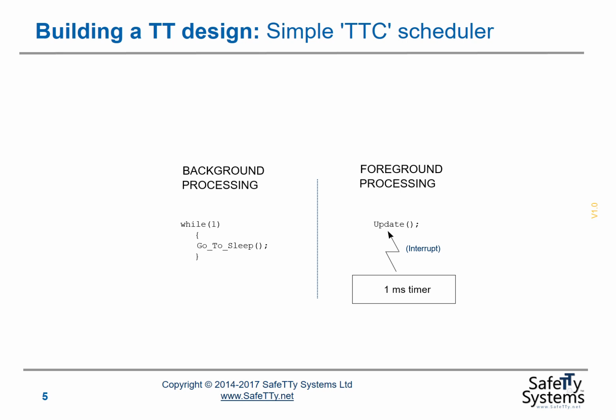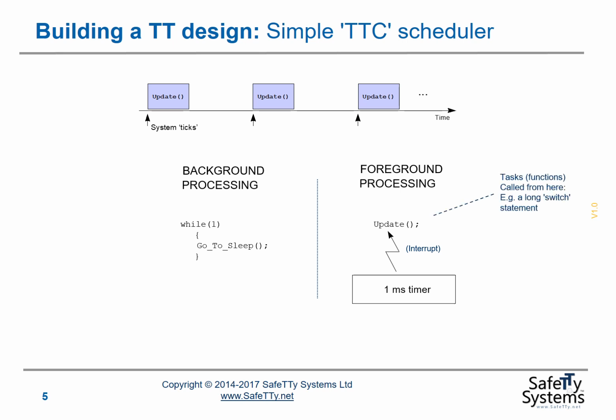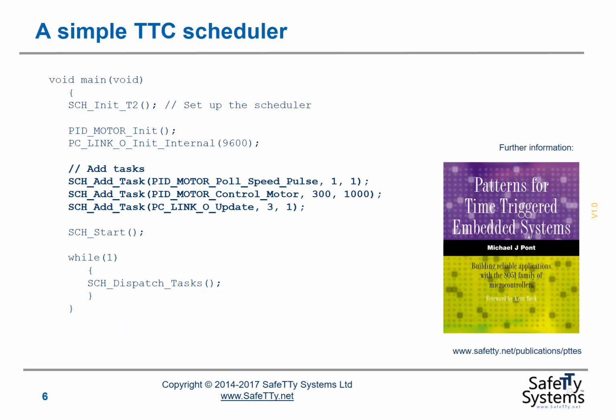So we start the course by looking at a very simple form of TT scheduler, which was based on a timer ISR. We discussed the fact that this gives us a simple time-triggered cooperative scheduler, but it's not a recommended platform for most safety-related systems. We looked at another simple scheduler, this one as described in the PTTS book. Again, this is a good platform for reliable embedded systems, but it has very limited monitoring capabilities, and again, we suggest that you don't use this in safety-related systems.